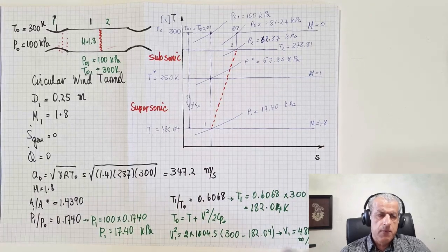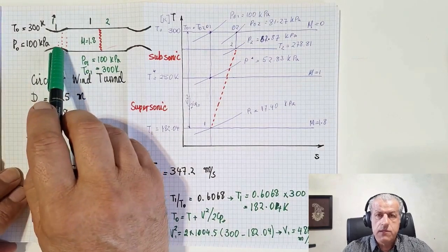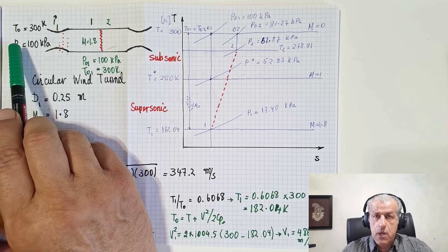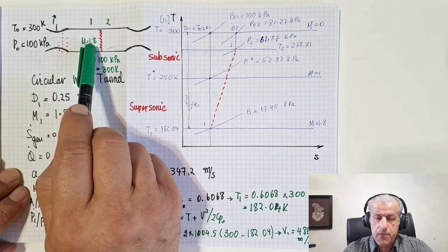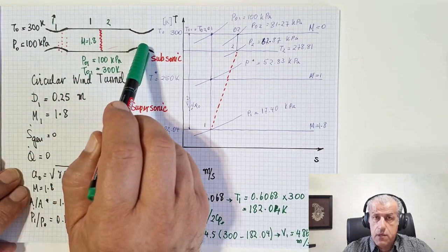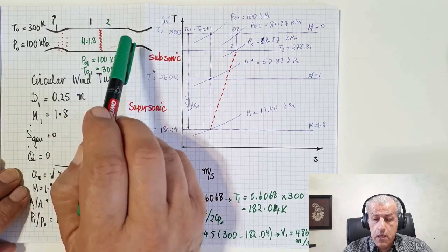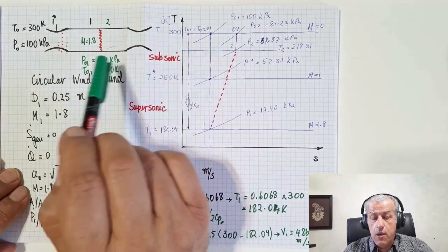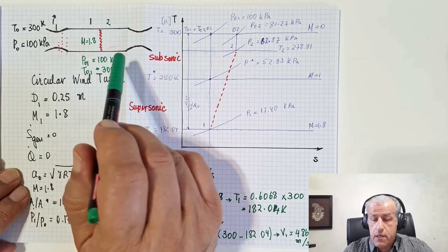As you remember, when we calculated the throat area for the nozzle, our knowledge was the total pressure, the total temperature, and the Mach number at the test section. Now, for the diffuser, conditions have changed. Before the shockwave occurred, all the throats along the line would be the same. But now, as the shockwave has occurred, conditions have changed.